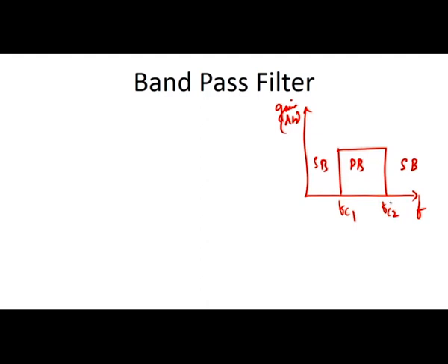If you divide this filter response, the first stage is the response of the high pass filter and the second is the response of the low pass filter. In the high pass filter, initially the signals are attenuated, and only after the lower cutoff frequency FL do the signals get passed through the filter.